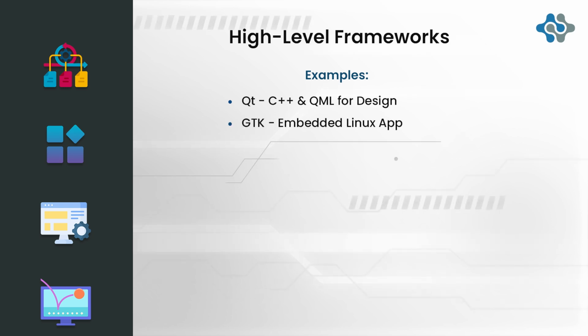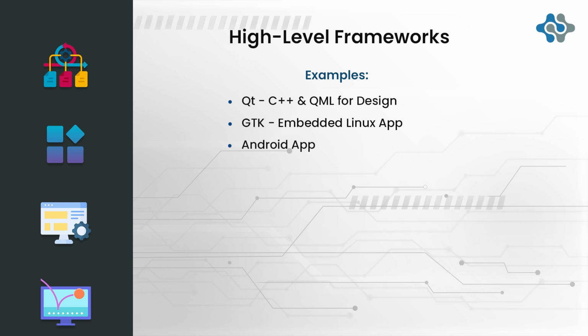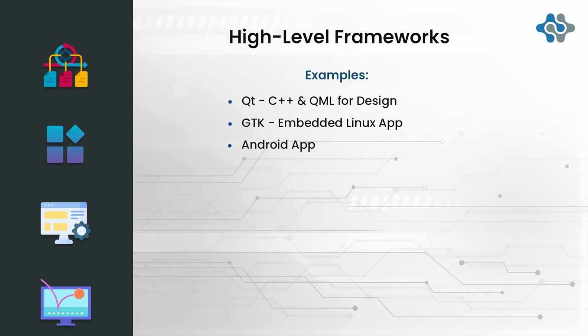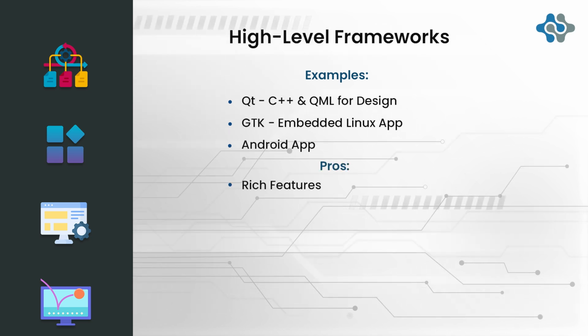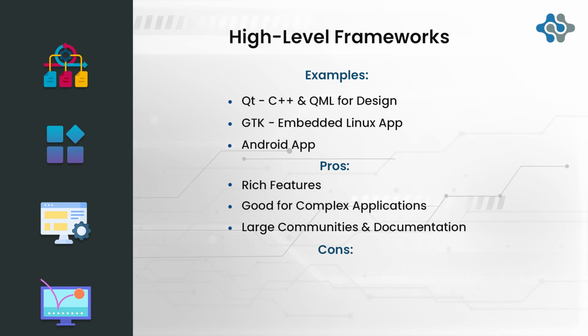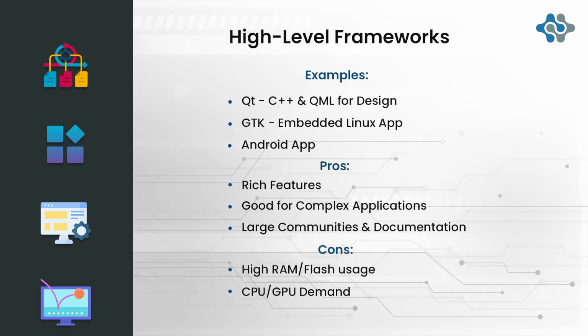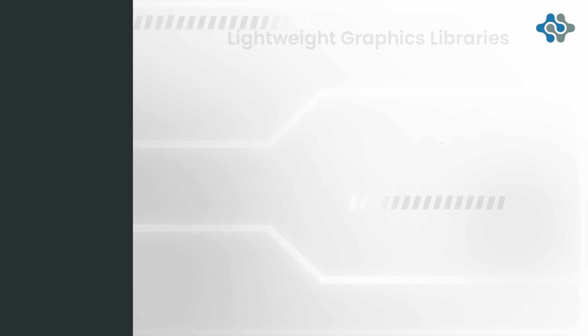Sometimes GTK is used for traditional desktop-like embedded Linux app development. Android can be an option in this category. Pros. Rich features, excellent visual fidelity potential, good for complex applications, large communities, and documentation. Cons. Resource intensive, needing high RAM, flash usage, and CPU-GPU demands. They can have significant commercial licensing costs per seat or per device.